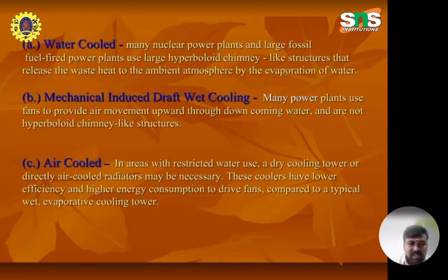The third one is the air cooled cooling tower. In areas with restricted water use, a dry cooling tower or directly air-cooled radiators may be necessary. These coolers have lower efficiency and higher energy consumption to drive the fans compared to typical wet evaporative cooling water.